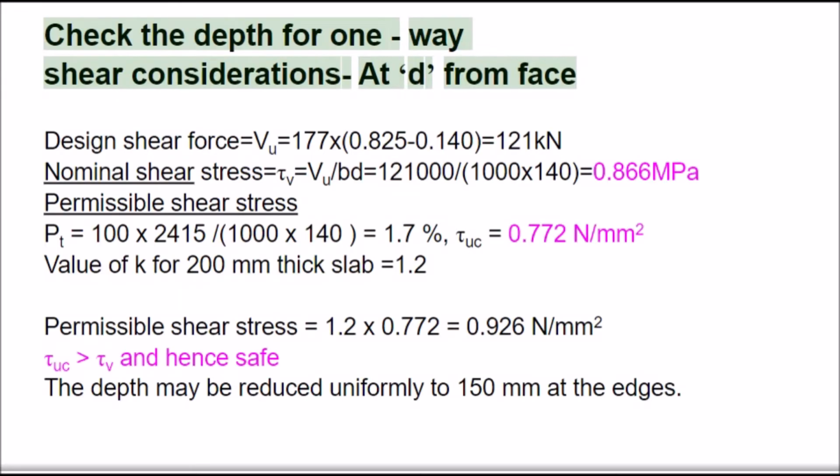Check the depth for one-way shear considerations at d from face. Design shear force equals Vu equals 177 x (0.825 minus 0.140) equals 121 kN.